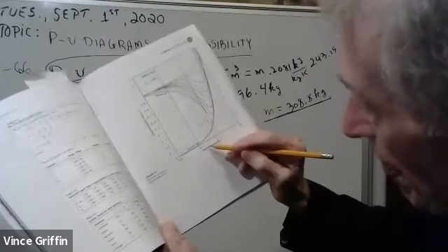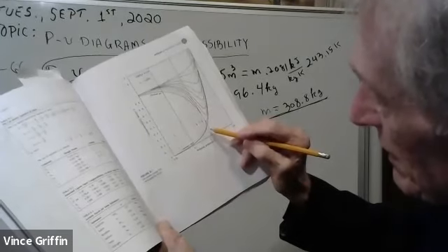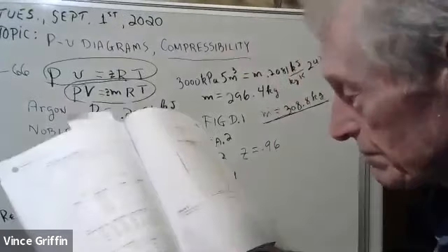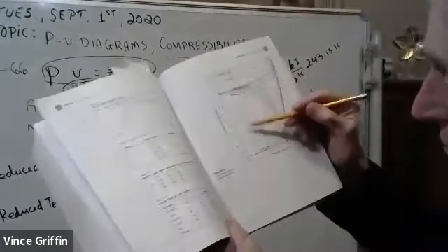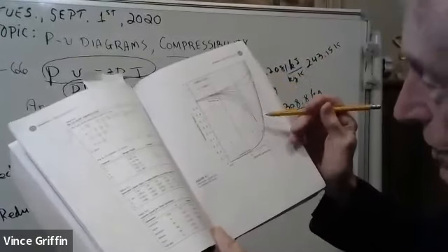I'm looking at the very bottom. It says reduced pressure, and I'm looking at 0.1 to 1. But then I'm also looking at those vertical lines there that say like 0.7, 0.8, 0.85, 0.9. I'm confused by, I guess, those two sets of numbers. Those are reduced temperature lines. Those vertical lines are reduced temperature lines. Okay.